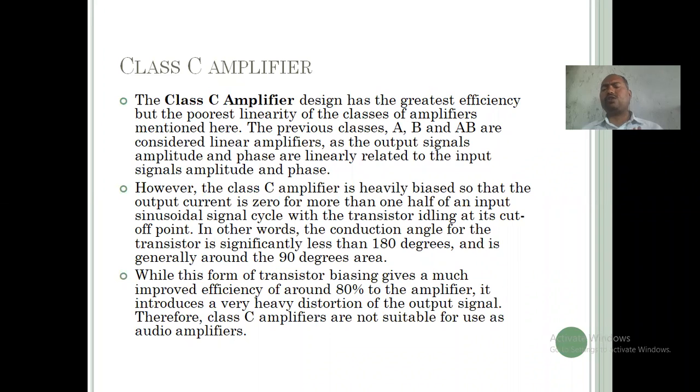It is nothing but distortion, and distortion is not acceptable in communication. That is another reason it should not be used in communication. So that's why it is not suitable for communication or for an audio amplifier. An audio amplifier handles signals of 20 Hz to 20 kilohertz, and in voice communication no distortion is acceptable at all. If distortion is coming, whatever voice is transmitted from your source should not go towards the destination. So the class C amplifier is not used at all in voice communication.